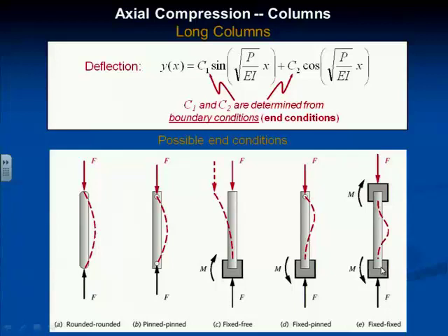So the reference on which all is based is the rounded. That would also be the same for pinned, by the way. If I put a pin through this and a pin through this, the pin is a rounded thing, so that's essentially the same as rounded. But if I had a round end here and a round end there, I'd have point contact on both ends theoretically, right? I don't recommend that as a good way to do it, but that's the reference, okay?